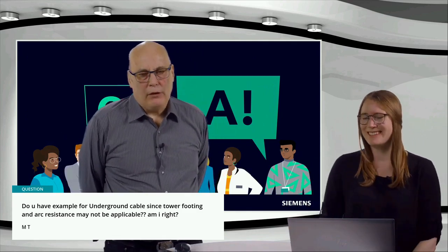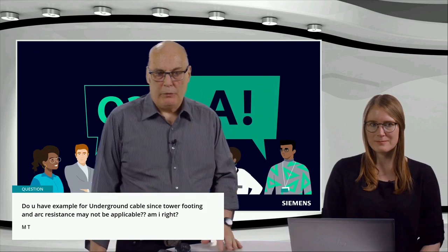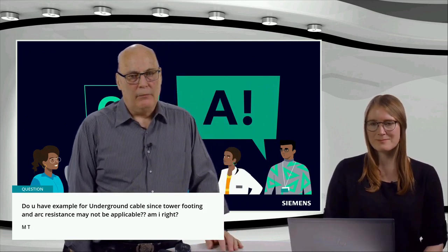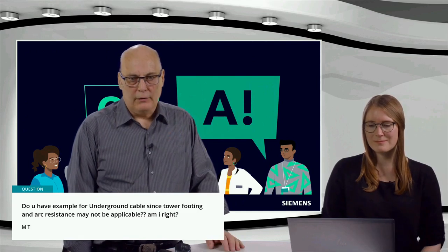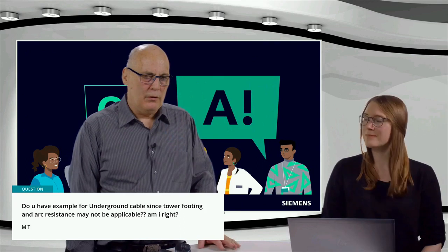Maybe you can. If you have underground cables, obviously you do get an arc in the dielectric of the cable, but you need to calculate that in a different manner, because it's not the same as the arc in air. And typically you would use a rule of thumb, a certain arc depending on dielectric, but that one has to be discussed separately. There's not that many parameters or information on that. For medium voltage, I have some data, but for transmission cables, I don't have data.